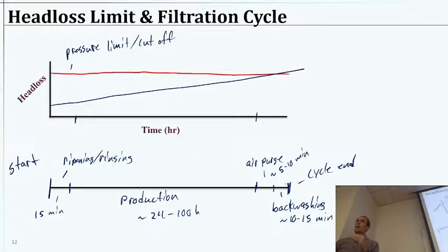So in these filters, we actually let them automatically readjust their own pressure just simply by gravity. If the flow rate slows down a little bit, it's going to have more water loaded onto it, so the height will increase and it will match the flow rate. So we can feed the filters at the same rate, let's say some number of cubic meters per second. Well, the filter gets clogged, and so it takes more pressure, but it's automatically rebalancing because there'll just be more water sitting on top of the filter. And that's why we describe it as a head loss.